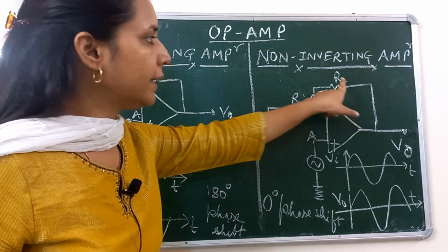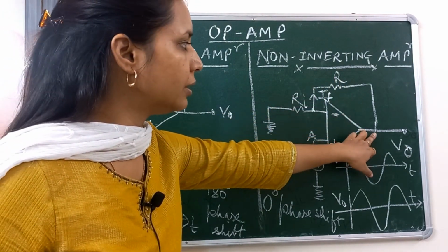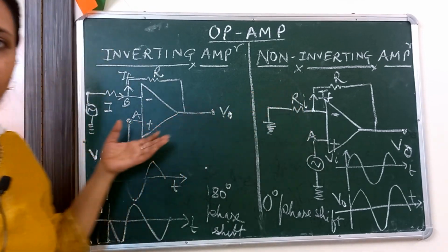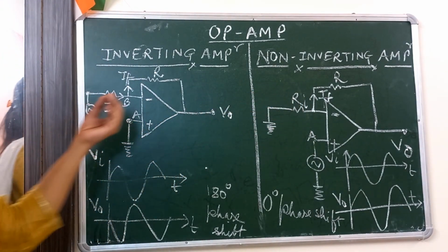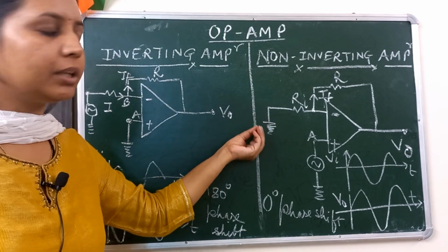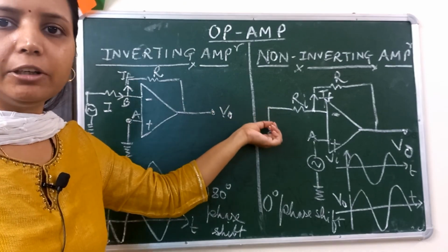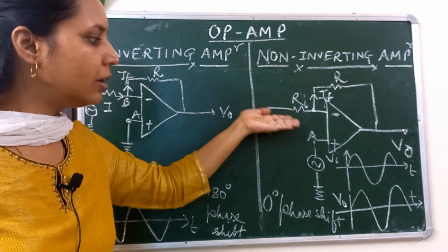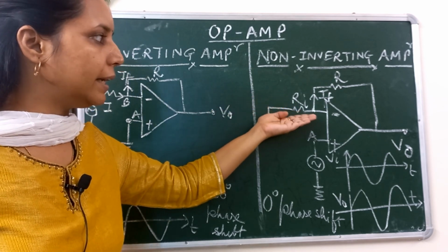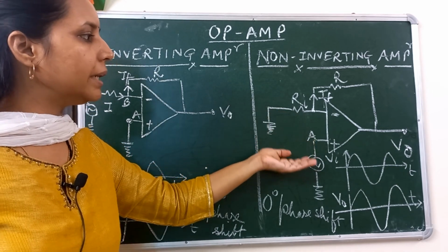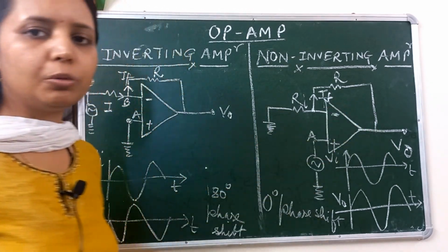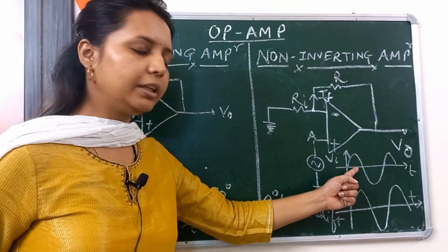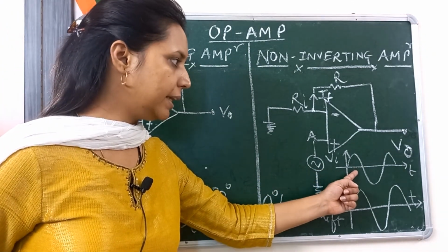There is a feedback network coming from the output terminal to the input wire. Why are we using closed loop here? Because using a feedback network increases the stability of the circuit. If you give an input signal or any input voltage at the input end, you will be getting a non-inverting output at the output terminal, which can be seen here with the waveform of the circuit.